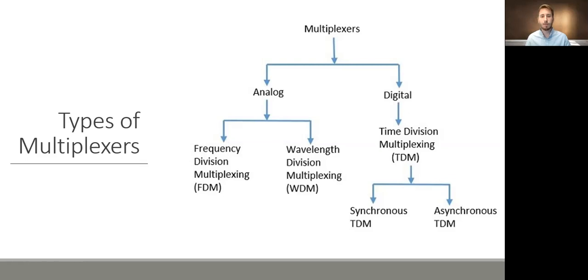This is used a lot of times for analog, and that's actually why I chose multiplexing as my topic. I wanted to multiplex some analog signals coming from sensors and then send those through a transmitter. This transmitter has one data stream, so I wanted to multiplex these multiple analog signals and then send them through the transmitter. To do this, the only way I could was to do time division. So you split it up, and we'll talk about this soon. But anyway, that's kind of why I chose this topic.